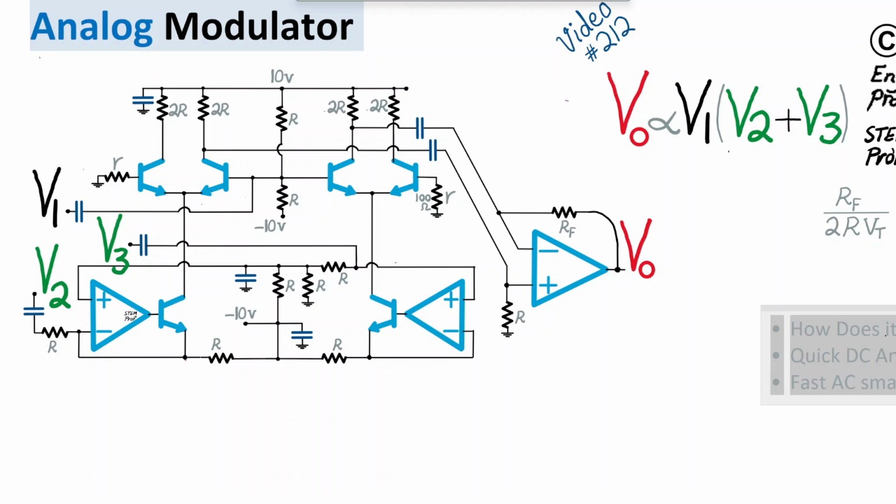At the bottom of the circuit, you can see we have negative 10 volt, and there is a voltage divider between these R and R. So basically, as a result, there will be negative 5 volt at this node because no DC current can flow this way, because one, it will hit the positive terminal of op amp that cannot take current, and the other one will hit the decoupling cap that is basically separating DC, and DC cannot flow through it. So we have negative 5 volt here.